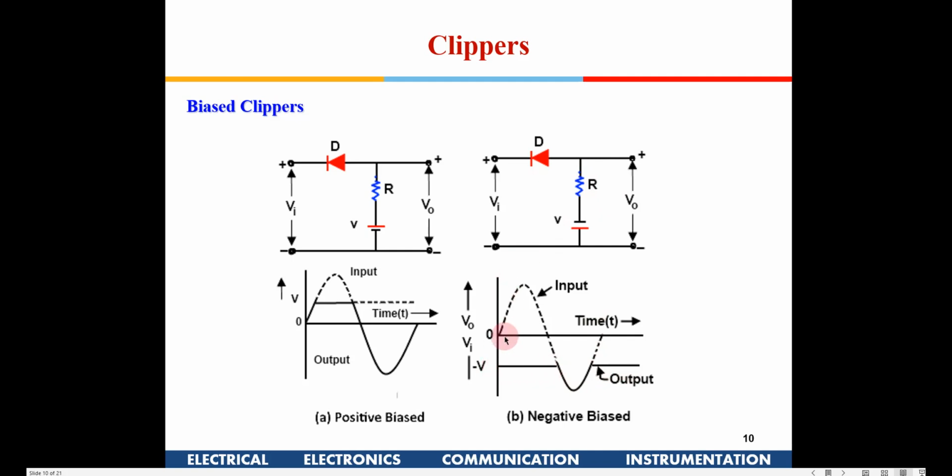Okay, understood? So initially the signal is 0, right? If it is a 0 out here, so see, this signal is 0 out here, but this is already negative given out here. So this diode remains reverse biased, right?